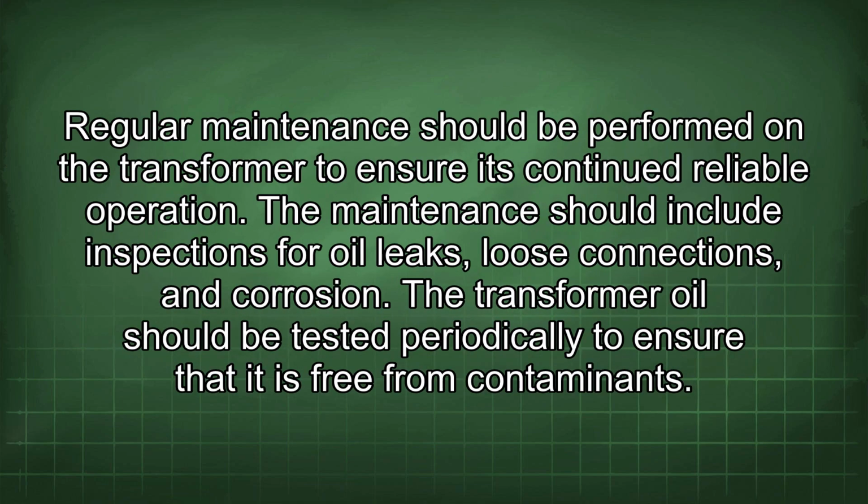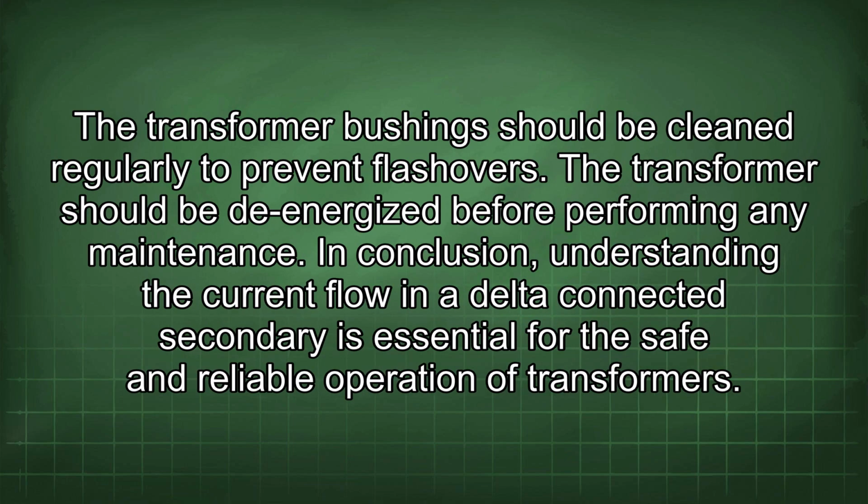Regular maintenance should be performed on the transformer to ensure its continued reliable operation. The maintenance should include inspections for oil leaks, loose connections, and corrosion. The transformer oil should be tested periodically to ensure that it is free from contaminants. The transformer bushings should be cleaned regularly to prevent flashovers. The transformer should be de-energized before performing any maintenance.